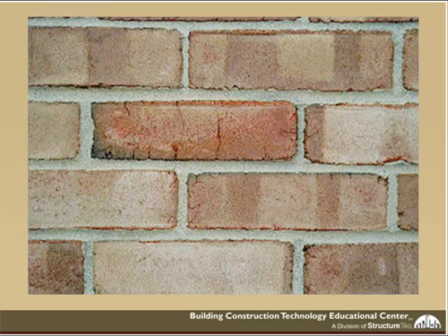A couple of examples of some test openings in some wall systems. The upper left is showing what happens with materials that are not durable. We got some cracked flashing showing there and heavy corrosion of the steel angle. On the upper right, you can see splits in the membrane flashing.